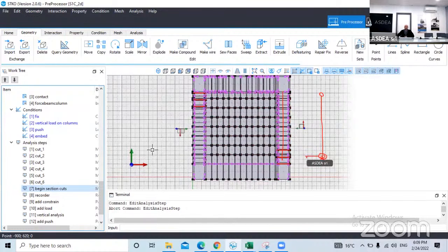But she needed to model it with continuum elements for a series of reasons, because she needed to take into account stirrups and the contact between infill and concrete. So she needed to model the concrete frame with continuum elements. Instead of having a column element, she has a set of 2-dimensional elements with all the discretization in finite element meshes.